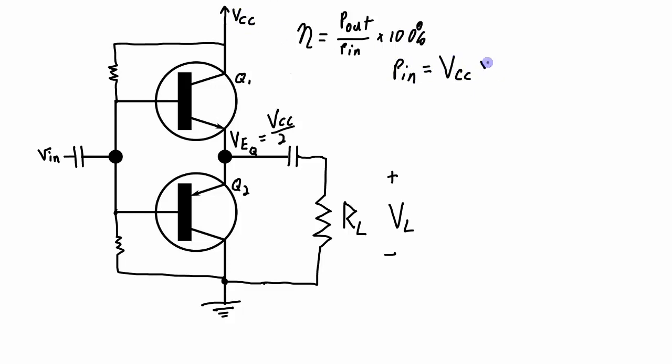And very simply put, it's going to be the voltage, VCC, times the current provided by the source. So that voltage will be constant, but this ICC is going to be changing. And there's actually two components to that ICC. One of them, let's call this I base bias. So that current is what's going to flow here, and that's going to be a constant, and that's simply going to be dependent on what resistor values we have here.